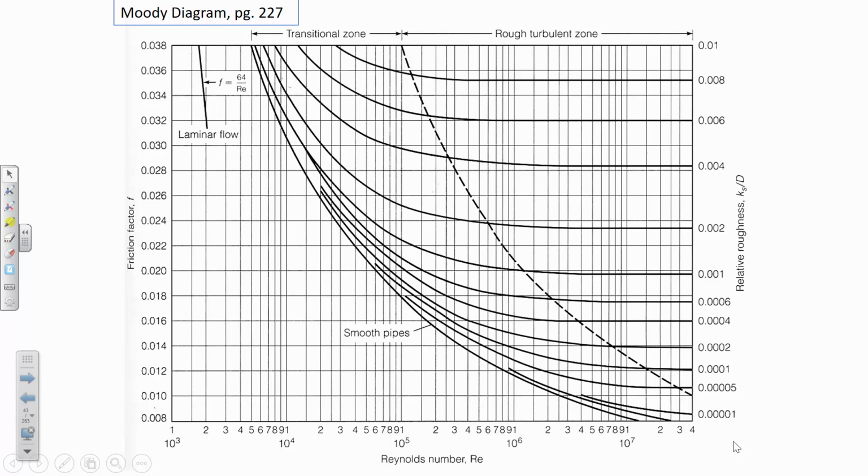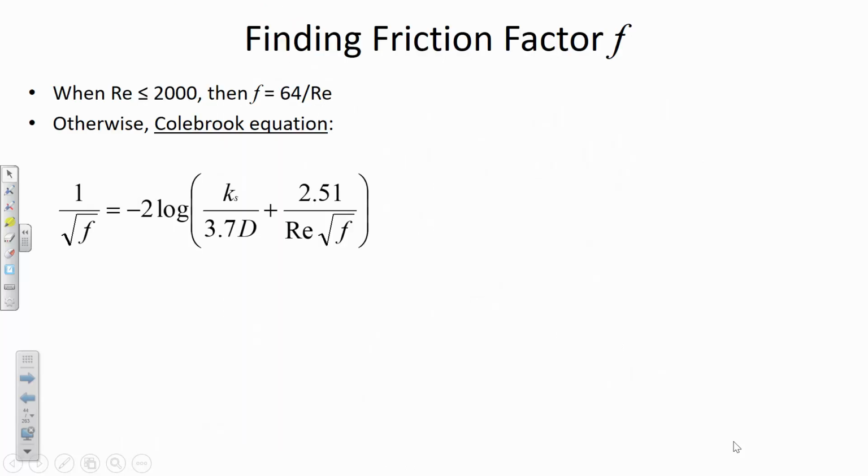And so the Hazen-Williams equation is all well and good. It's very convenient. It's very simple, but it's just not realistic that the friction factors wouldn't change. So the Darcy-Weisbach equation does account for variable friction factors, but so far you've been kind of limited to using this figure for calculating the F value. And that can be inconvenient if you have a solution that has to be solved over and over again because maybe you're making design changes, or it could be an iterative solution where you don't yet know what the flow conditions are.